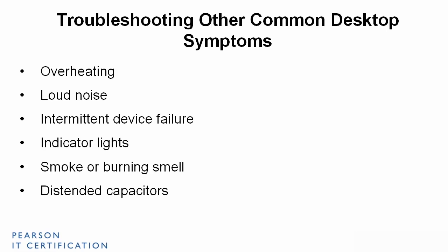And this was a big problem in the first decade of the new millennium. Basically between 2000 and 2010, there were a lot of devices that were manufactured with bad capacitors. And the capacitors failed, and they called it the capacitor plague. It was an electrolytic issue which caused the capacitor to burst, basically. Usually, they wouldn't just explode, they would just kind of crack. So your motherboard might still be okay, and you just have to replace the capacitors.